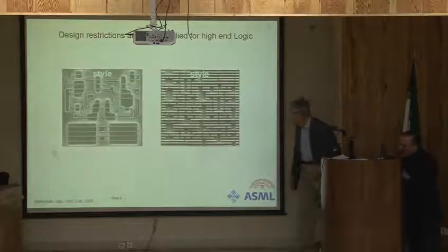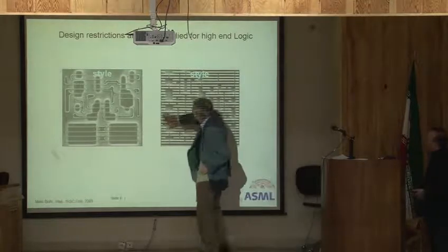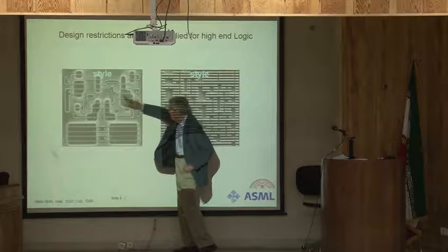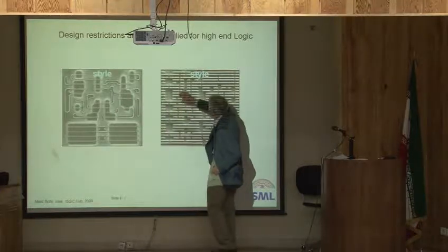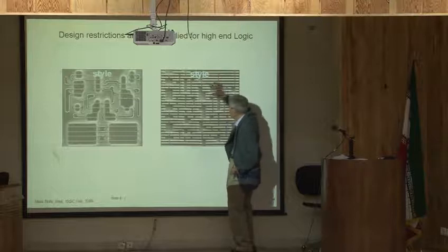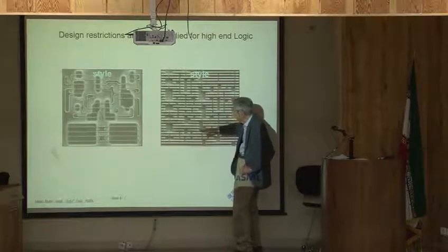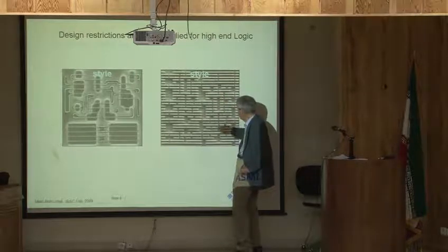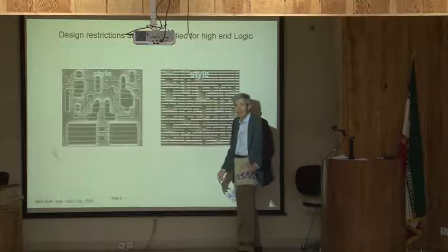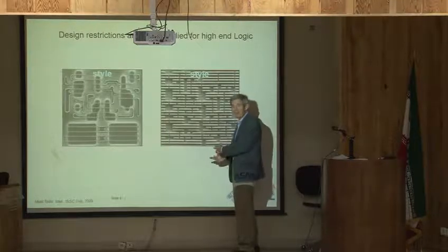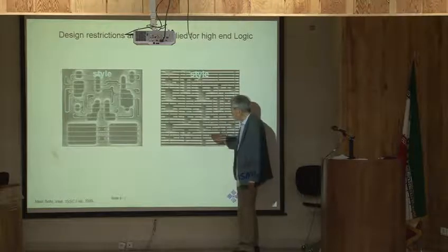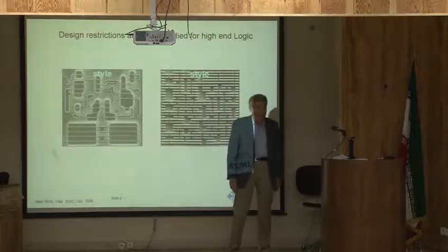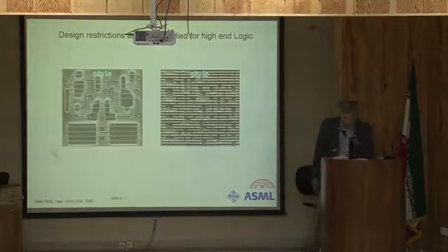Yeah, there we go. So this is done with the, you can't read the printing there, the 65 nanometer node, and these are some of the features that we're making. This is the 32 nanometer node, half the distance. Now you see, what they've done is they've made the grating patterns. It may be a couple of levels of exposure, and then with a different tool, they've simply cut these things to length. So now the device designer, the circuit designer, has to work out ways in which they can make a fully functional circuit using these very simplified patterns. That's what they're doing at the moment.